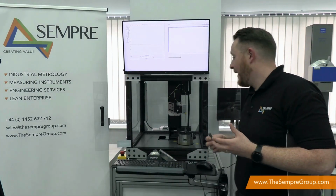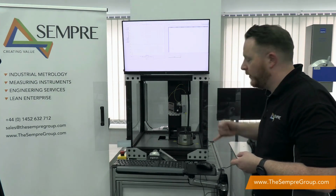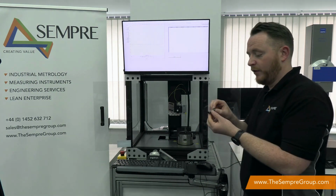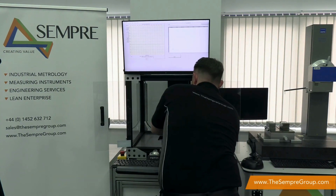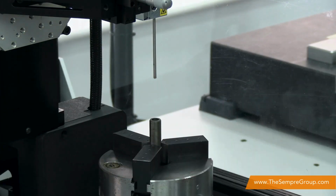So now we're going to look at outputting a roughness value. What we're going to do is take a profile measurement on the internal of a component. We're actually going to swap the component over. So I've got a through diameter here, so it's a continuous diameter through the center. So what I'm going to do is take our threaded feature out and place our other component into the chuck. Okay, so we've got that placed in.